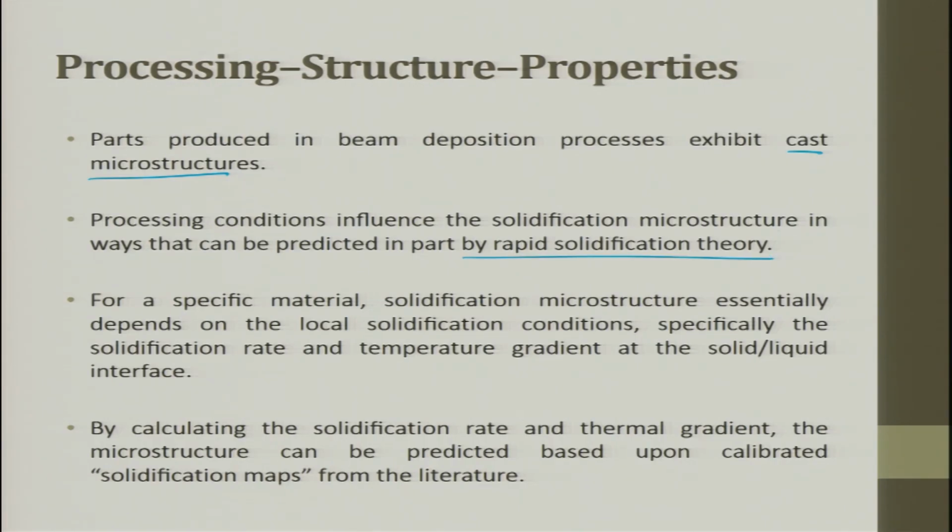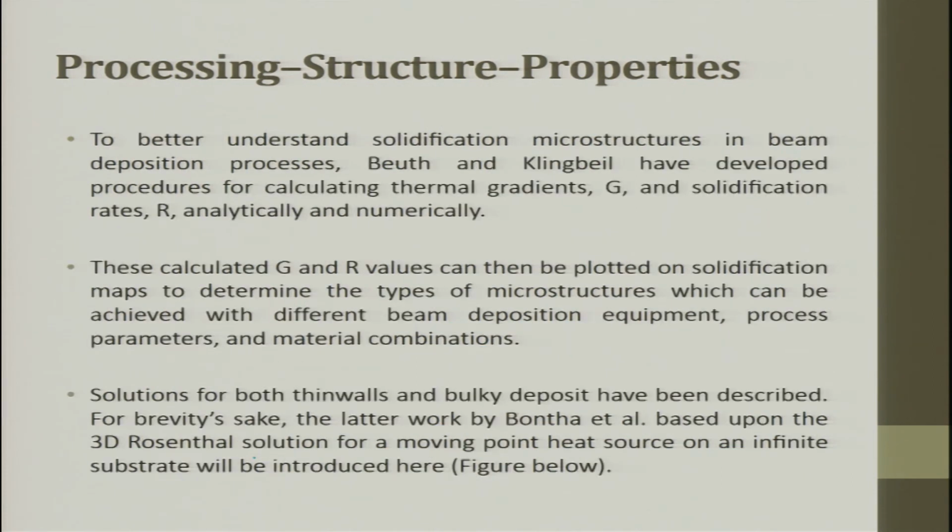Grain engineering is the latest topic at the research front. People have identified that if I start doing engineering on the grain size distribution and grain shape, I can dictate the material property. For a specific material, solidification microstructure essentially depends on the local solidification conditions, especially the solidification rate and the temperature gradient at the solid-liquid interface. By calculating the solidification rate and the thermal gradient, we can try to predict or play with the microstructure.